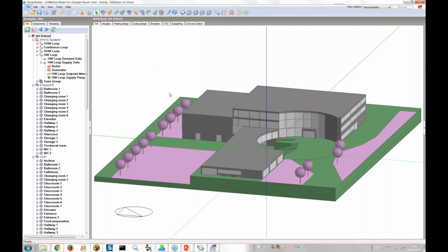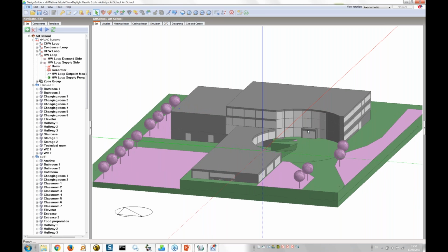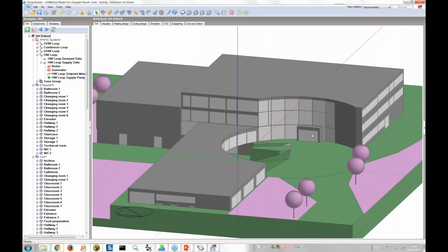There's a number of smaller improvements, but there's a nice little one that I'd like to show you right now. Here we can use the mouse wheel to zoom in and out from the point where the cursor is positioned, whereas before it didn't used to do that. So if I want to, for example, zoom in on this little section, this surface that's protruding from the curved surface there, I'd position the cursor on that and then just use the mouse wheel to scroll in.